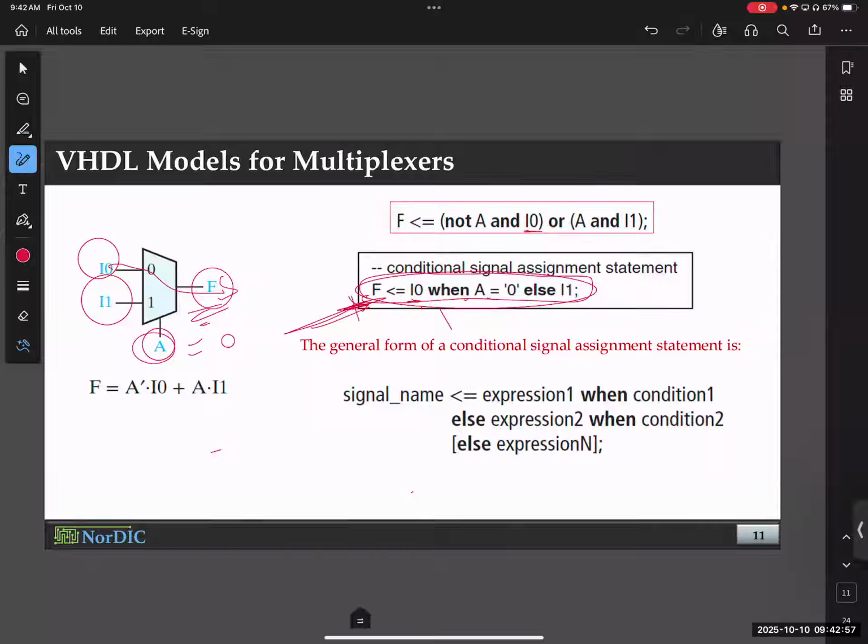For example, you have 8 digits, 101111 and so on. It's called an opcode, right? Operational code. For that particular opcode, it will activate a portion of the hardware. Maybe that's an adder, and it will add. So that opcode basically represents the plus symbol. So plus is not being converted into an ASCII code. It is being converted into an opcode, right? You see my point here?